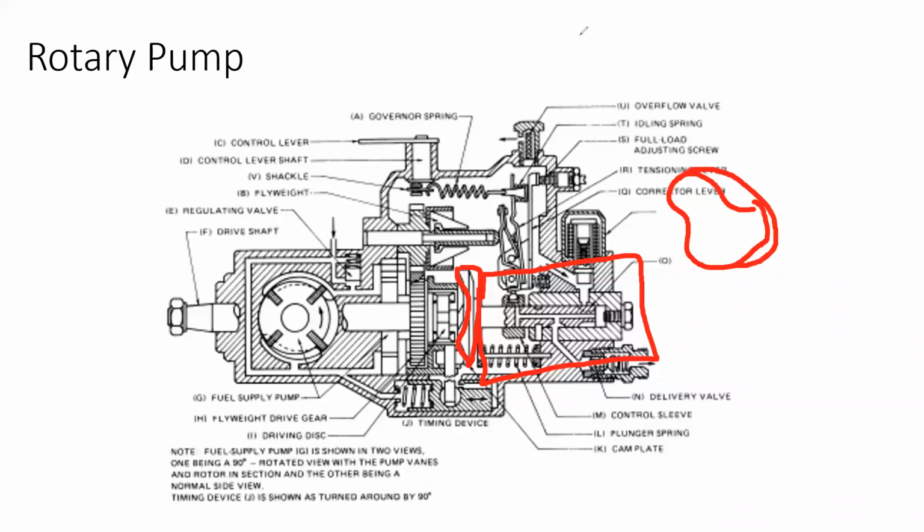I don't know whether you know the rotary cam. Anyway, this is a rotary cam. When the pump is rotating, the rotary cam is also rotating. When the rotary cam is rotating, it is connected to this metering rod and the plunger, which are both as one. So the fuel is filled in this section over here, and the fuel will be pressurized, right?